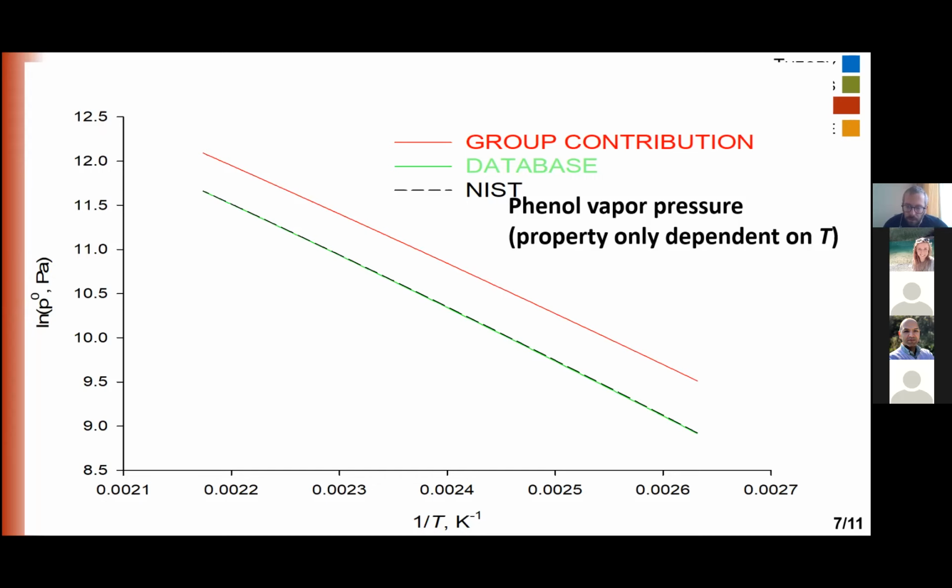the database. Then I built phenol using the UNIFAC groups, and I used the Jacopo method to estimate the vapor pressure of the component. This is a method that works more or less like UNIFAC. What they do is regress a lot of data from the literature, splitting the molecule into different groups, for example, CH3, CH2, etc. So, without knowing the property, you can simply build your molecule and estimate the properties.